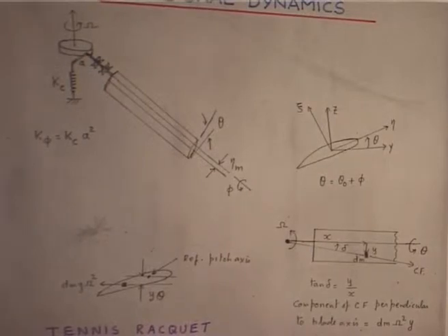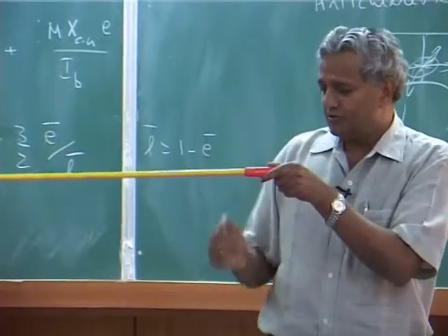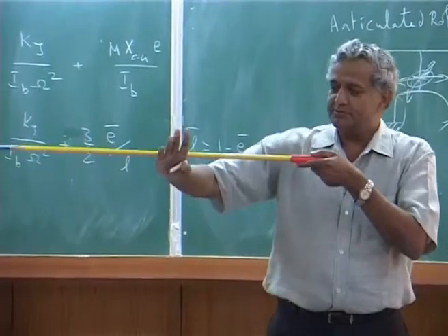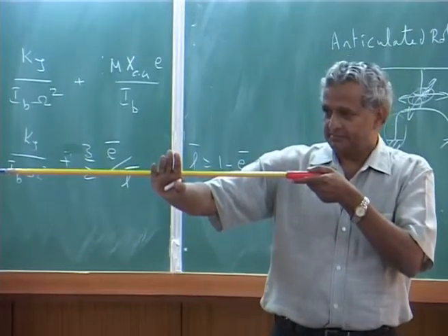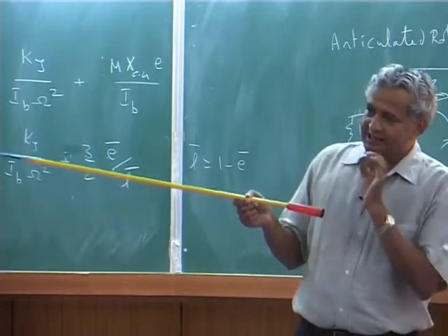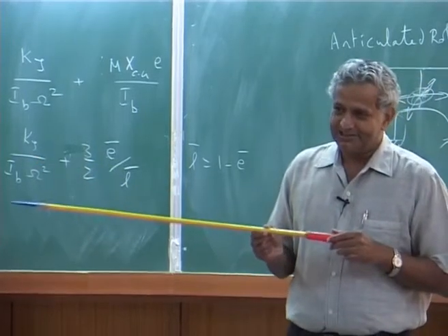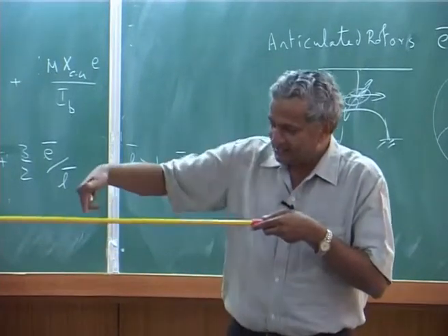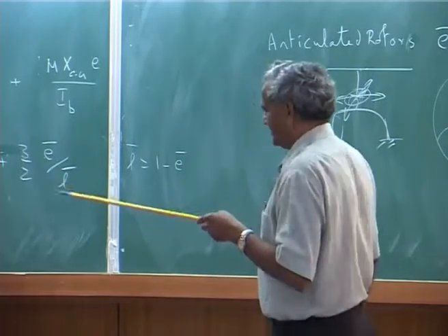Now, what is my dynamics? There is a spring, blade is rigid, but it has two bearings. The bearings are free to rotate, but the restoring force is given by the spring. When it rotates, suppose you keep it at a pitch angle, in this case you do not treat the blade as a line, you have to treat the blade as a 3D body. This lateral distribution, for simplicity, I will show.